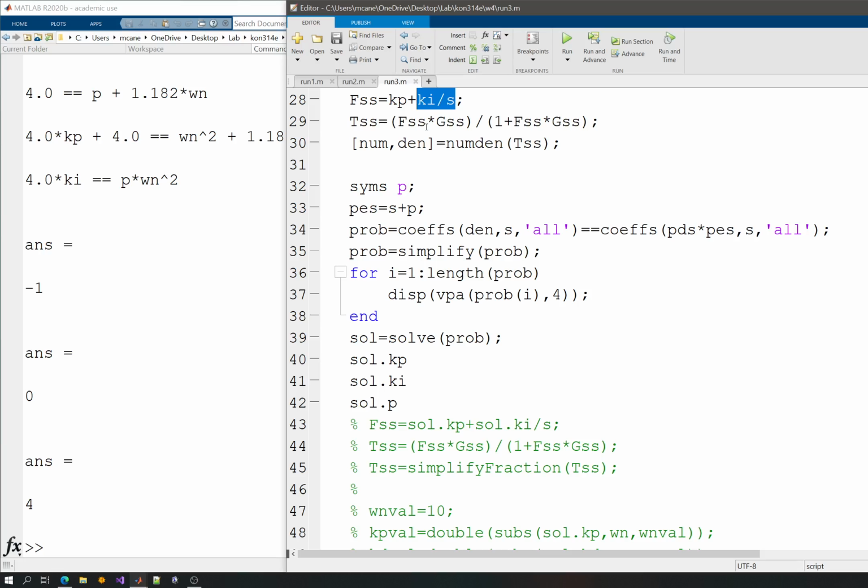But if we insist on having PI controllers, this means that at least you should have Kp and Ki parameters, since a PI controller consists of P and I parts. You might end up with an I-type controller, that might be the case, but if you end up with a P-type controller, it is also possible, but you are basically not placing an s at the origin, or you don't have any integrator.